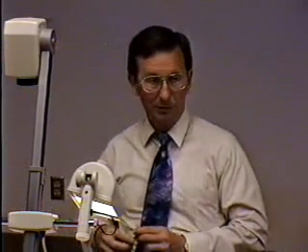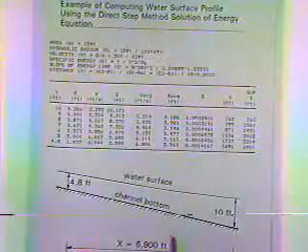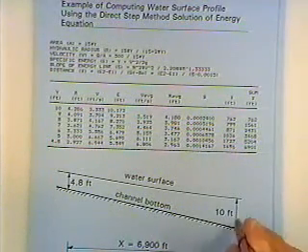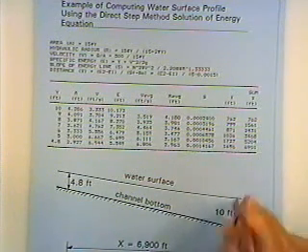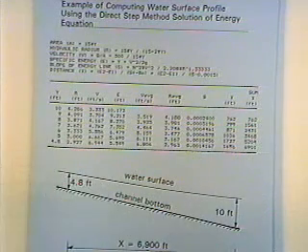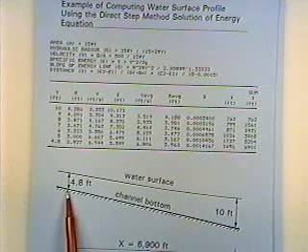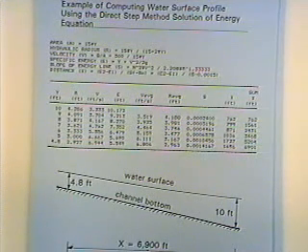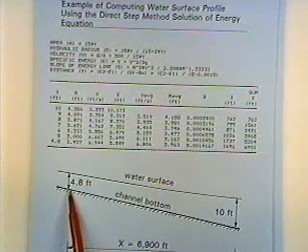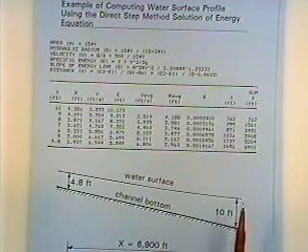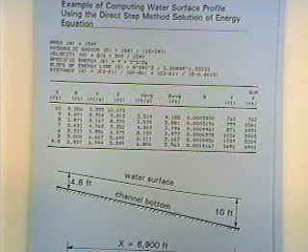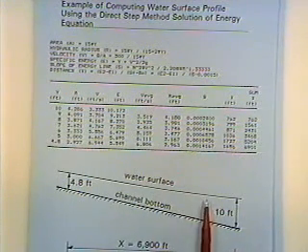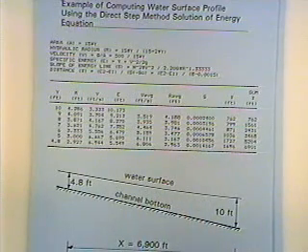On the bottom here, we've drawn the schematic. Coming horizontally out of the paper is the river, 10 feet deep. Then we've got the concrete channel emptying into the river. Someplace up here, the frictional forces and the gravity forces are in balance, and we've got a uniform flow depth of 4.8 feet. But this 10 feet is throwing it out of balance. We've got a backwater effect, a non-uniform flow. And we know there's no hydraulic jump, so I can draw that in as a smooth, gradually varied flow. What we'll do is compute the depth at different locations along the channel.